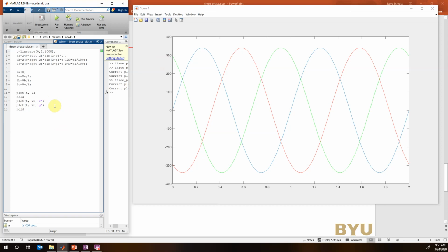So we can look at the sum of the three. And you see, like we showed before, they're going to be zero. You can see at this first point, I have about plus 300, a minus about 300, so those sum to 0. I pick another point. This one's like 350, and then I have 2 of the 175s, and so you see it always sums to 0.